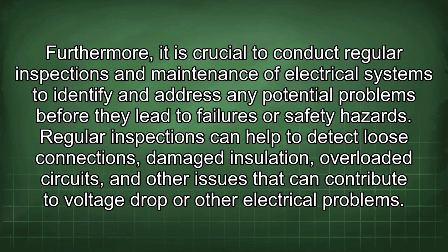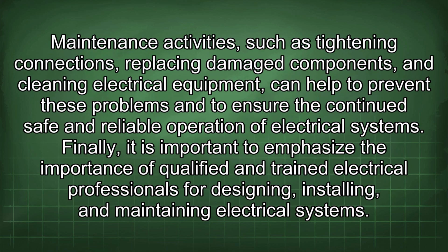Regular inspections can help to detect loose connections, damaged insulation, overloaded circuits, and other issues that can contribute to voltage drop or other electrical problems. Maintenance activities such as tightening connections, replacing damaged components, and cleaning electrical equipment can help to prevent these problems and to ensure the continued safe and reliable operation of electrical systems.